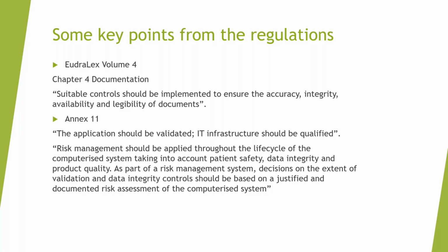So when you are going to be implementing, for instance, a new analytical instrument, you need to consider through risk assessment how that system is going to be used, what decisions will be made on the basis of the results obtained from those systems, and according to that risk level, you must ensure that you have adequate controls in place to ensure the data integrity, and it will also inform you as to the extent of validation and qualification that you will need to perform on that equipment.